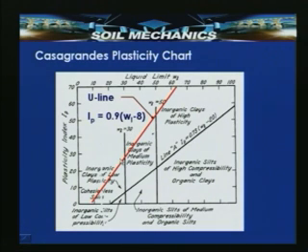Inorganic clays of medium plasticity are above the A line, but in between liquid limit 30 and 50. So, what has been done is that it has been subdivided into liquid limit 30 and liquid limit 50: low plasticity less than 30, medium plasticity between 30 to 50, and high plasticity liquid limit greater than 50. So, some cohesionless soils fall here, some inorganic silts of low compressibility fall here, inorganic silts of medium compressibility and organic silts fall here, and inorganic silts of high compressibility and organic clays fall below here.